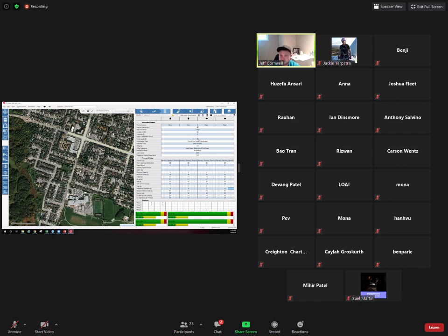So you'll notice that this intersection here is on a 90-second cycle length, and this intersection here is on a 240-second cycle length. So I'm going to just click this. The second button here is optimize split and cycle time. So if I want to create a 90-second cycle here, I can just go 90 for the lower, 90 for the upper, and then I'm guaranteeing myself I'll have a 90-second cycle. So that's one way, if you wanted to match cycle lengths, for example, of doing it.